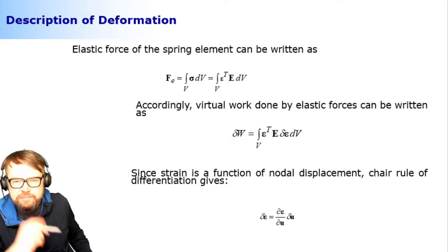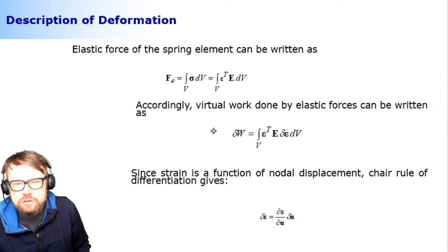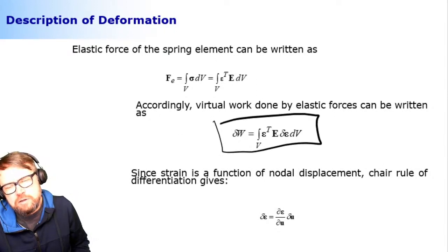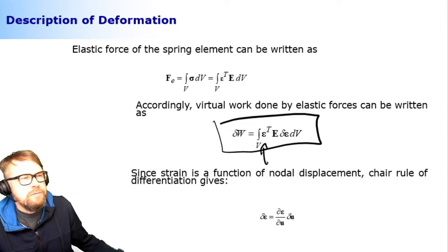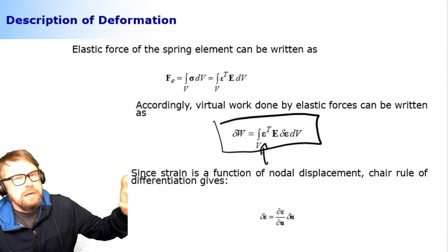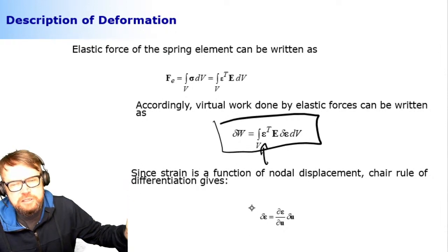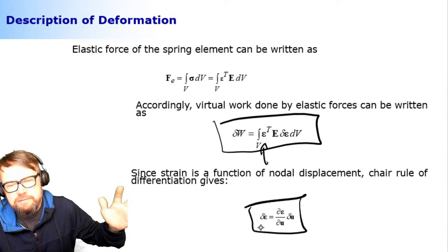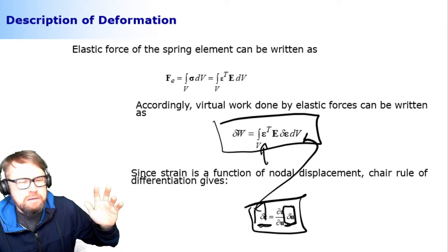This is how the elastic forces can be computed. This is pretty much the story that I just mentioned: the virtual work done by elastic forces. Now this is virtual work, so I could use energy or virtual work, it doesn't really matter. But again, look at what I have here. I have this strain, so I have to be able to relate my strain and displacement. And once I have my strain, then it's just mathematics. I can use the chain rule of differentiation to express this delta of displacement by using delta of nodal degrees of freedom. So all that will be more or less mechanical.